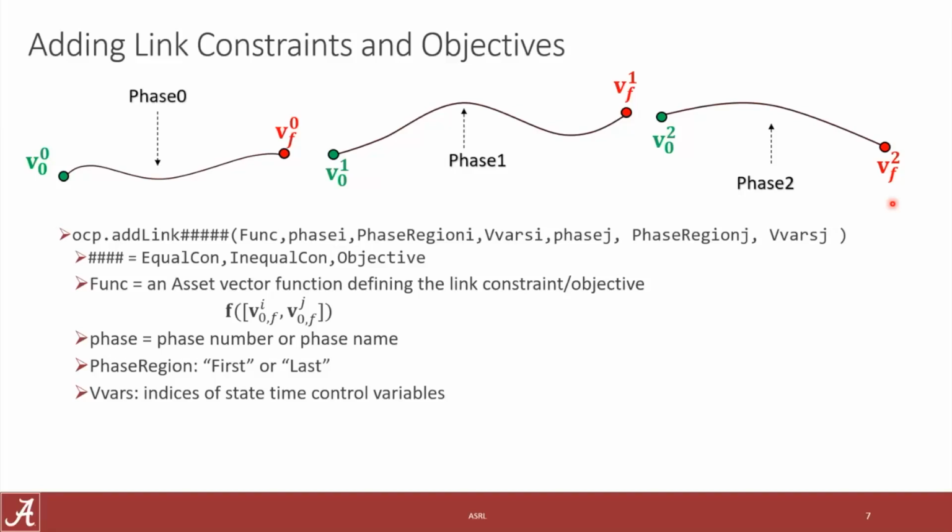It's not covered in the slides just for time. You can make the values of integrals of your phases equal to a static parameter. So you can put integral constraints on something, to say I would like to take an integral over some function on this phase, like the heat load, assign it to one of those static parameters, and then make all of those continuous in our different phases. So you can add different integration variables at the phase level rather than in your model, and then make sure those are continuous. That's actually put in there for things like those integrated heat loads.